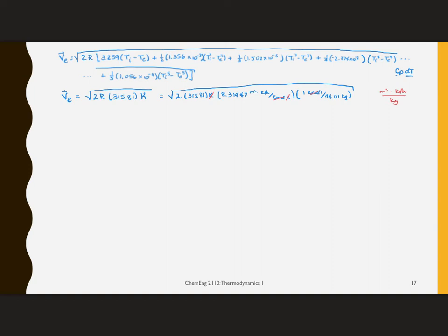That's garbage units. When I take the square root of it, I'm going to be even more confused. So what I need to do, I can evaluate this so far with my calculator, but the units are meters cubed kilopascal per kilogram. And now I know that a kilojoule is the same as a cubic meter kilopascal, and 1,000 meters squared per second squared is 1 kilojoule per kilogram.